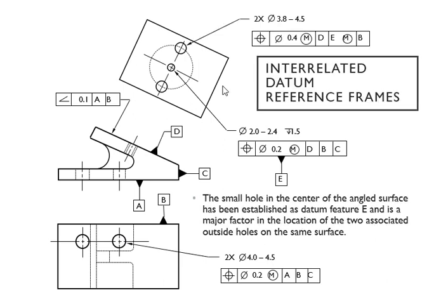And then the next one is this little one, which is the second one. It's going to be two of them on this side and on this side. So you can see, of course, here. And that will be controlled by the same D, and another new datum feature, E, with the maximum material condition right there. That is going to be right here. I put it on the control frame because it's difficult for you to put in this view. So that's just attached to there, so you know that it is referring to that little circle right there.